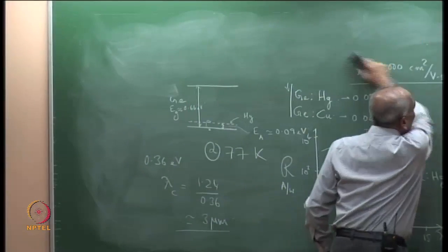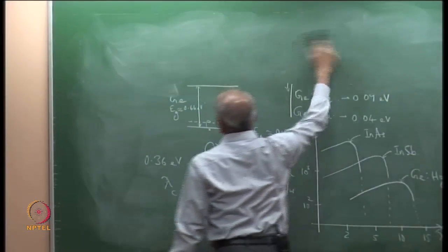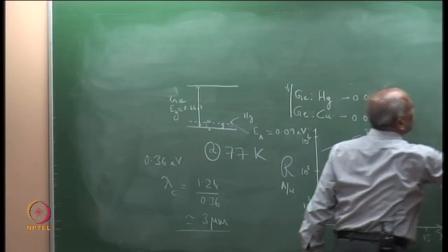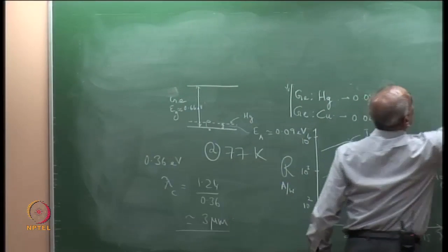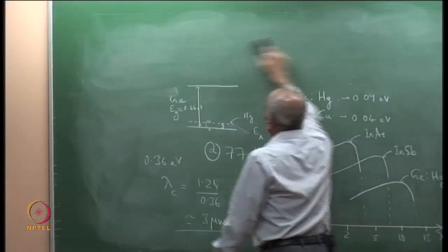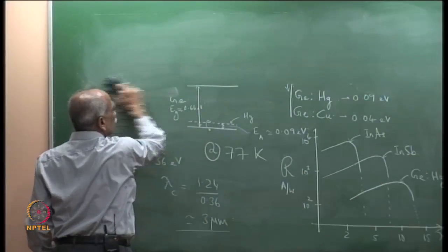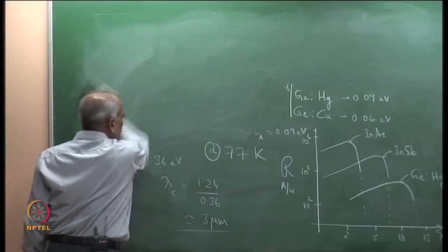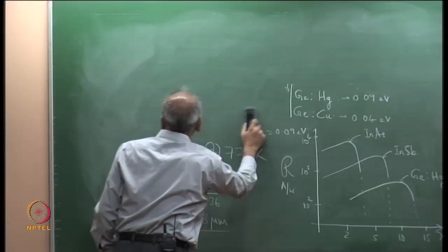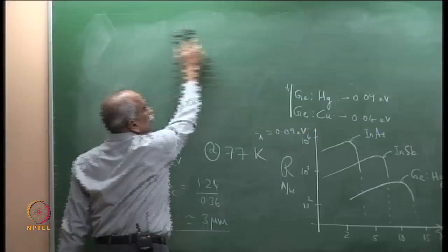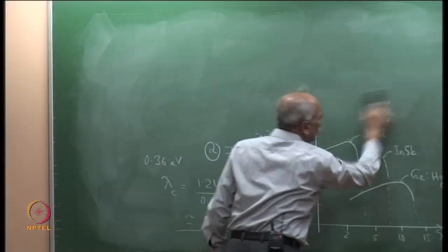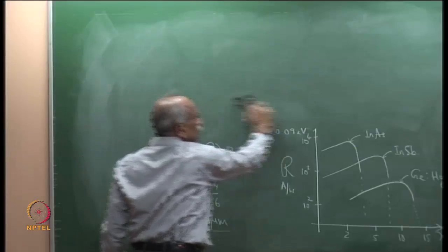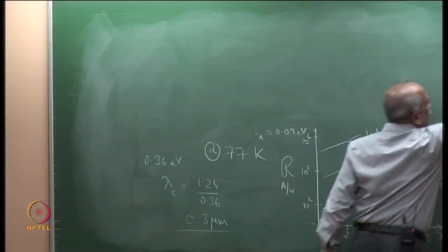So, we come finally to one high speed design which is widely used with photoconductors. As we discussed, one of the major problems is carrier transit time and recombination time. Recombination time can be reduced by using pure materials with minimum defects. And transit time can be minimized by using interdigitated electrodes.